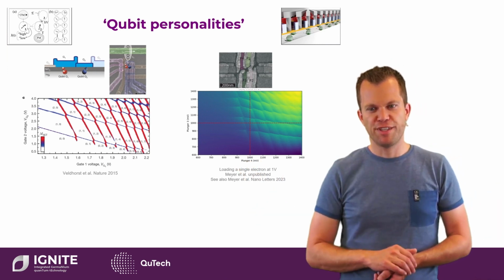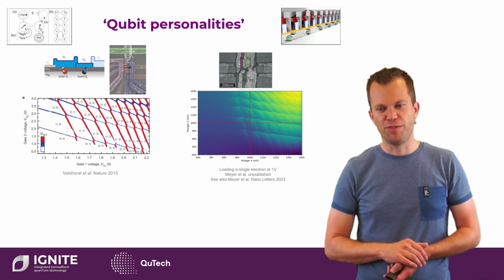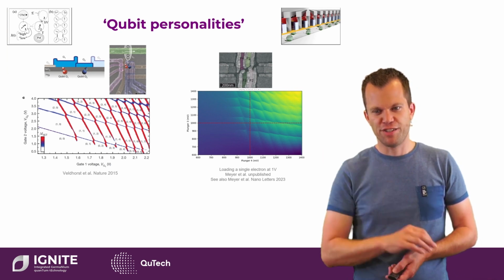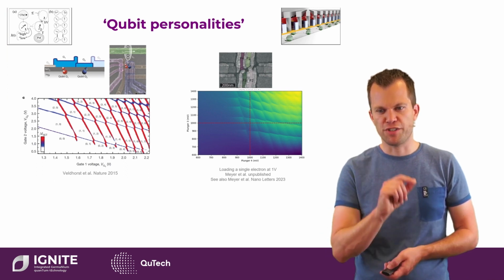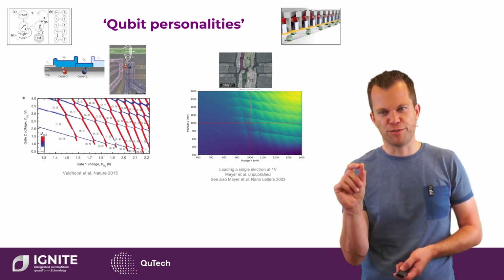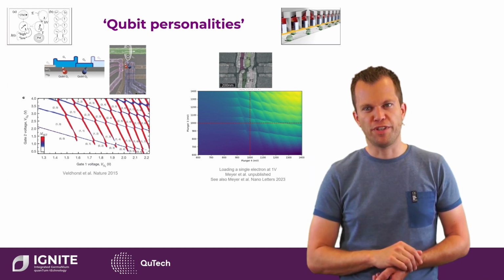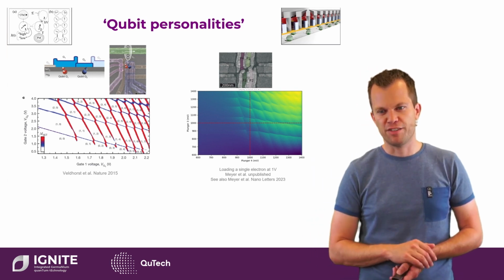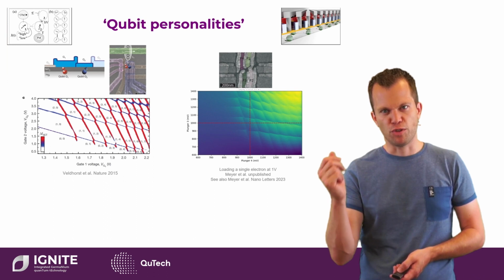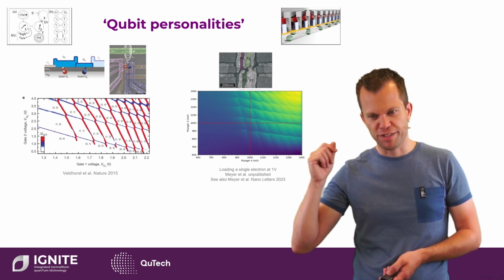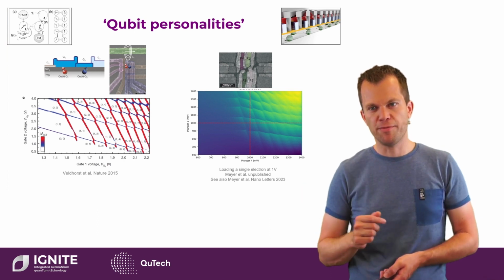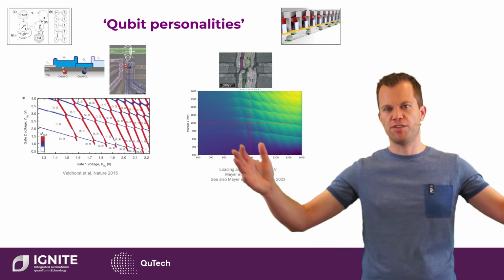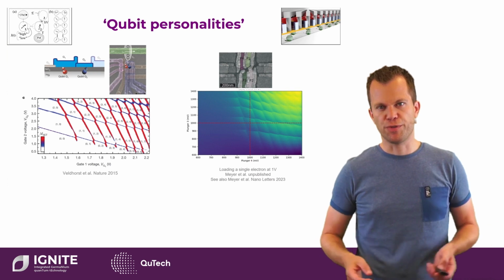On the right, you see an image of what we can do today. Here you see these dashed red lines, and you can see that for both gates, plunger 3 and plunger 4, at 1 volt, we can tune to a point where we have 1 electron in the system. So we can go to the 1-1 system with a single common voltage. And this may be key. Why? Now imagine that we have some large array with shared control.